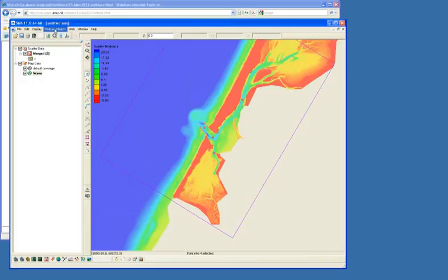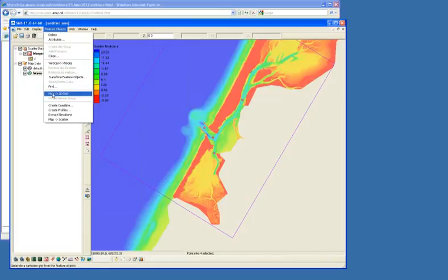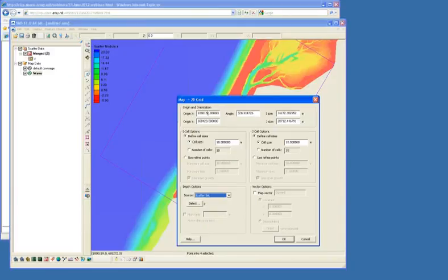And then we're ready to build the grid. So it's under Map to 2D Grid, which is under the Feature Objects pull-down menu. And we'll choose Refine Points. We'll give it a base cell size. I'm just going to choose 200 at this point. Turning off the inner growth, and then choosing a scatter set.